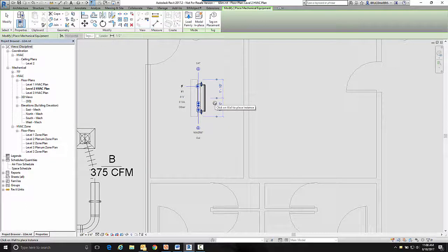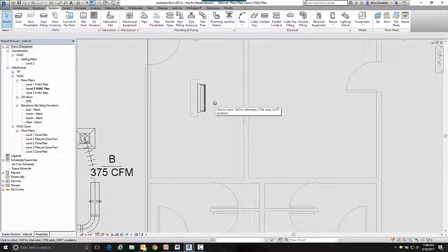So that unit was designed to be a wall hosted unit, which means the architect's walls would have to be in your file. And of course, in a standard MEP file, you're always referencing in the architect's background, or linking it, as Revit calls it.